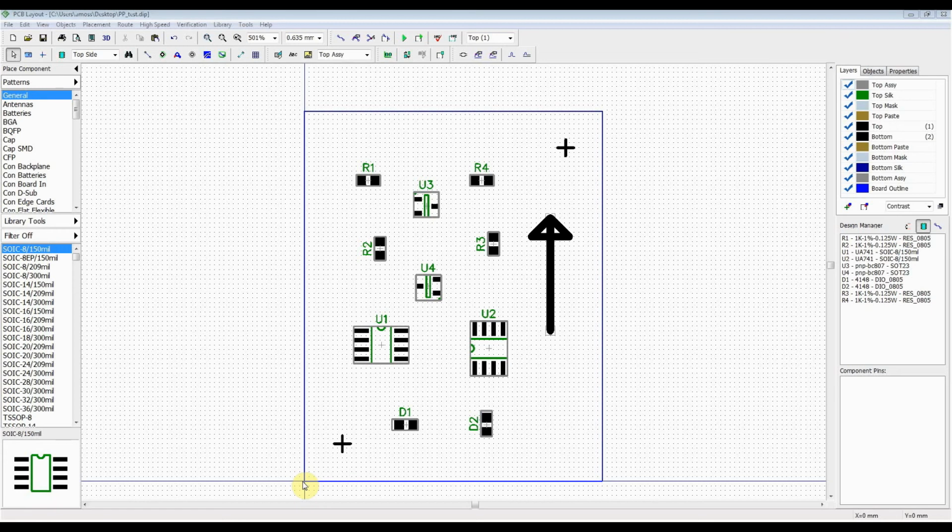And if you're putting this into the MV10 pick and place machine, the origins are all going to match up when you set the origin to the corner of the board. It makes things a little bit easier, though it's not a necessity. Other things, fiducials, bottom left, top right.